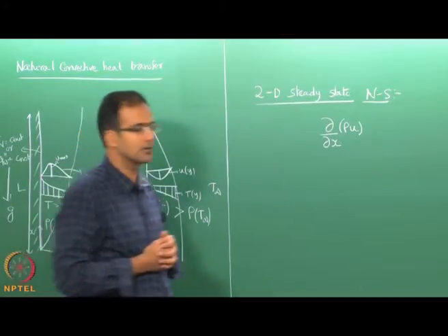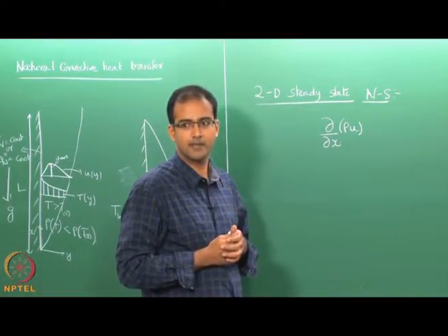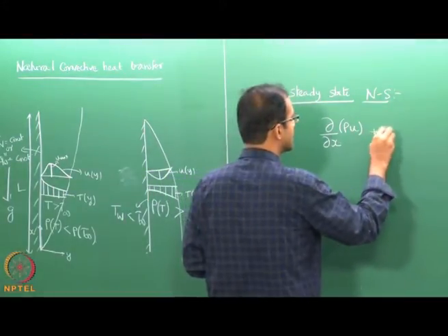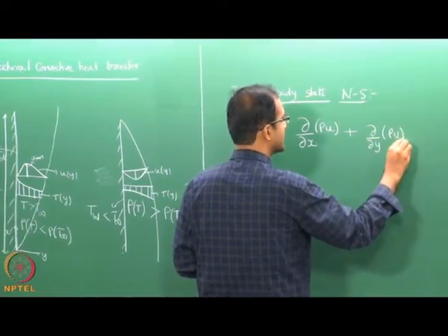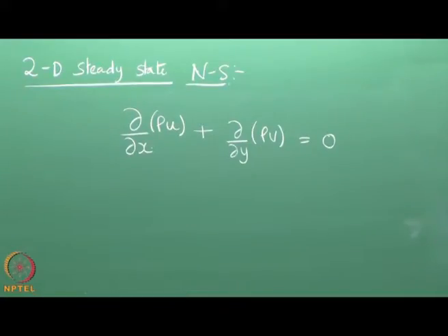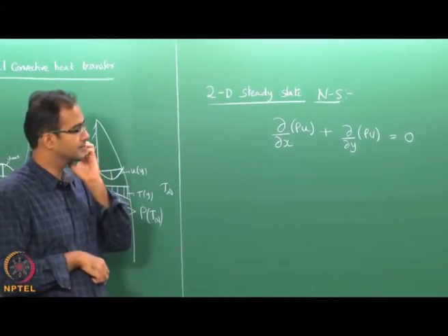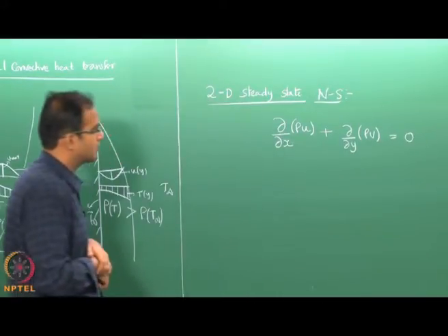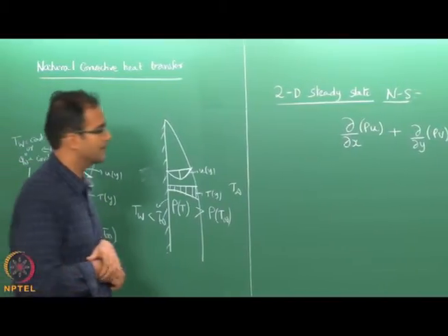So, locally it will look like it is a compressible fluid, because the density keeps varying with different position. So, you cannot therefore directly at a first cut say that this is an incompressible approximation straight away. We cannot directly pull density outside the derivative and say it is a constant, right. However, it was shown later by Boussinesq.